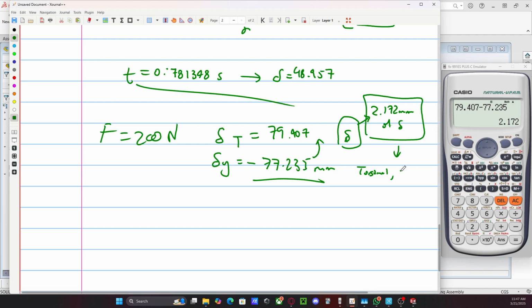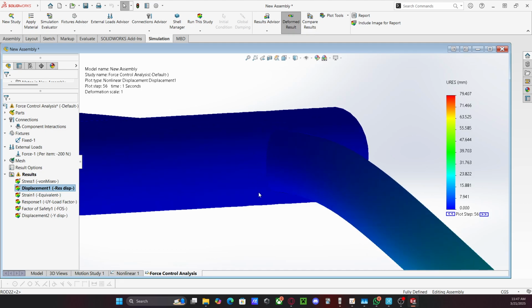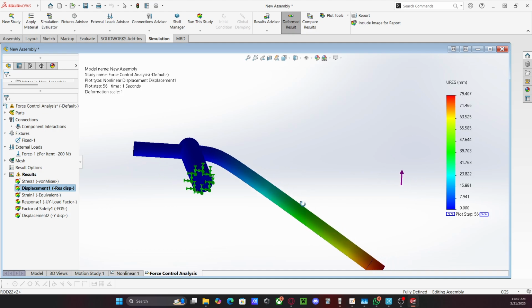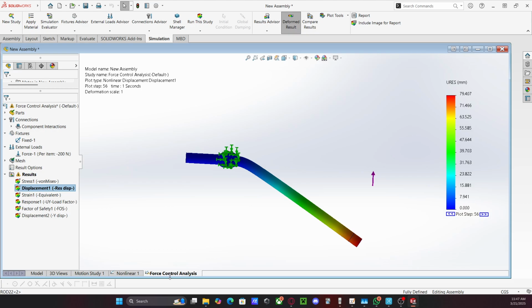We also have something called the section modulus, which you can use to calculate these values earlier. We can also have other effects. For example, over here, we didn't apply mesh control, so this might also have been attributed to the difference in values. Okay, so that is for force control.